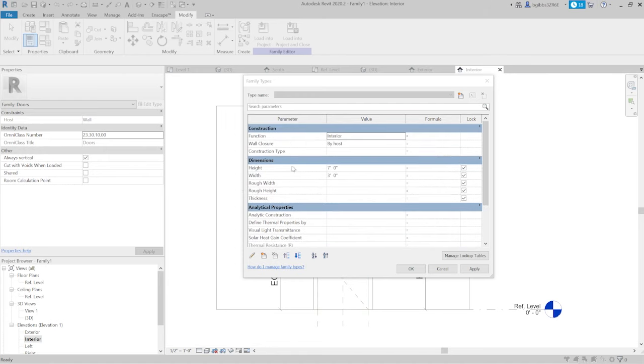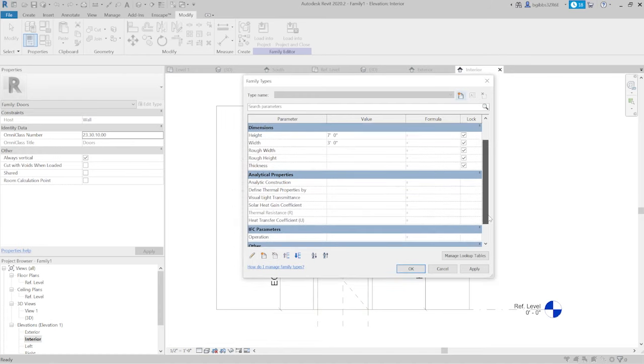They're very useful, of course, getting your height and width. Your rough height and width is definitely more construction based. This will be useful. These are locked, which means it's locked in the model. So if we add new information, for instance, a window light within the door, we can always put that height and width in here, or if you're locating it, how high it will be above the ground. And thickness also can be in that set of information.